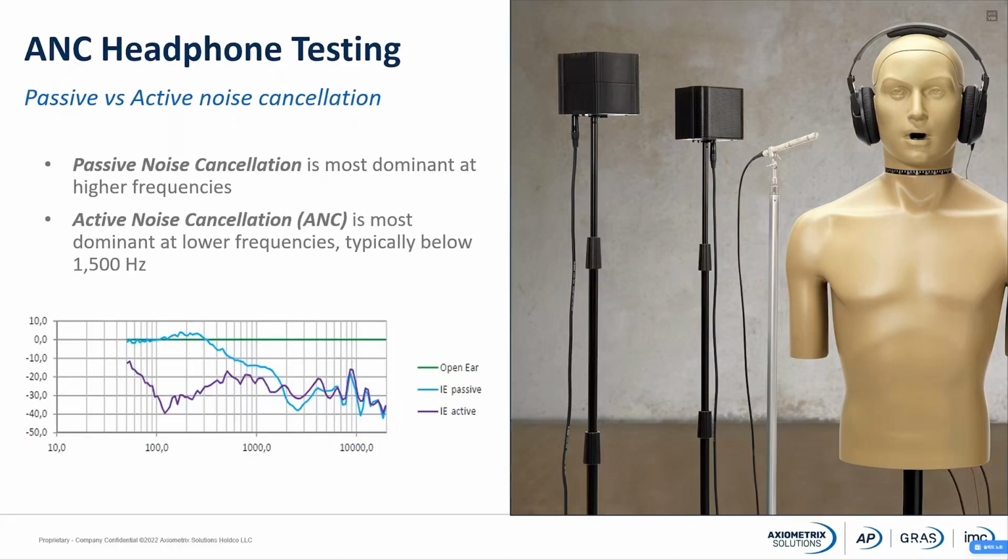So I would say that pink noise is a good signal to get an idea of the performance of the ANC, but it's not the only reference signal that we should use. Maybe pink noise is good enough for a quality assurance system setup, or for some quick measurement in R&D, but it shouldn't be the only type of signal that we use for this test.